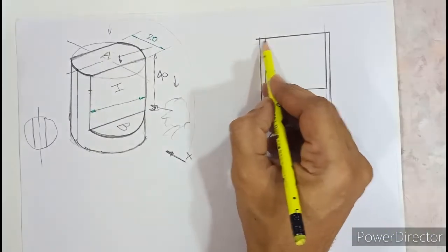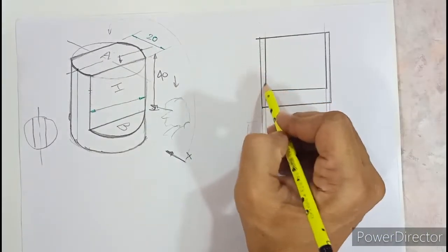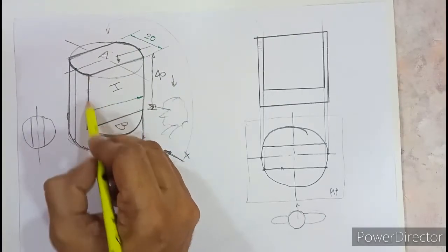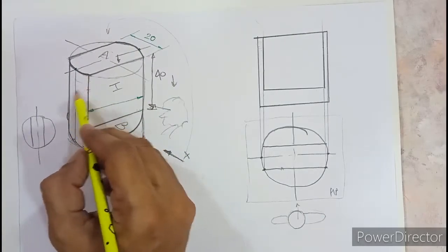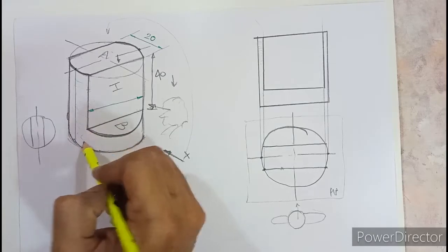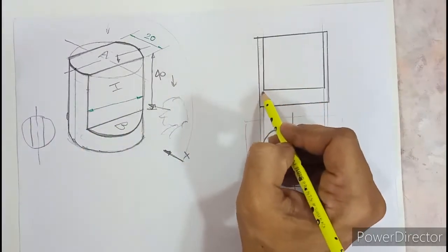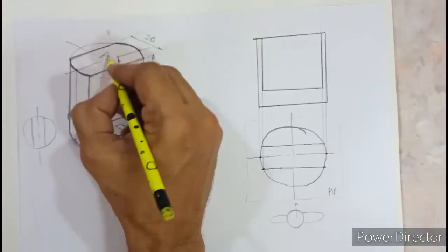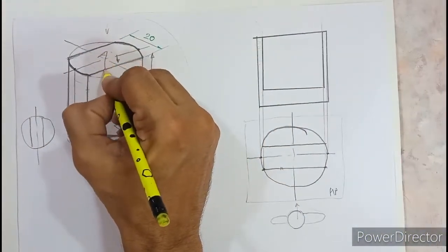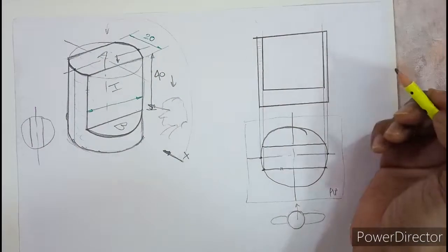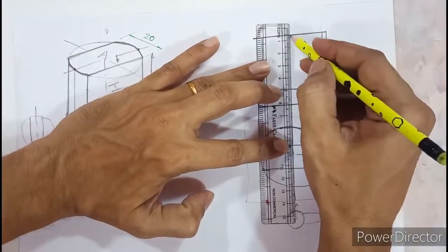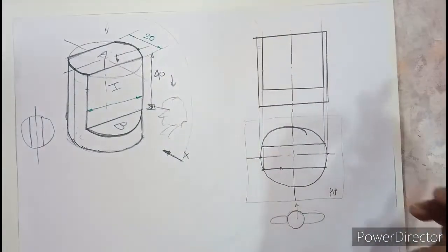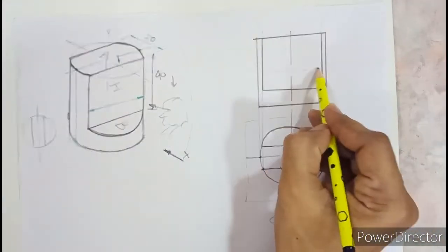So the gap between these two lines, actually it's a radial surface. So if you look in the front view, the gap between the black vertical line and the green line is nothing but the radial surface. It's a curved surface. So this portion is actually a curved surface all throughout. Now if you look at this diagram thoroughly, you can see that the axis of the cylinder still exists. So we need to draw an axis over here. So that is how this length can be found.